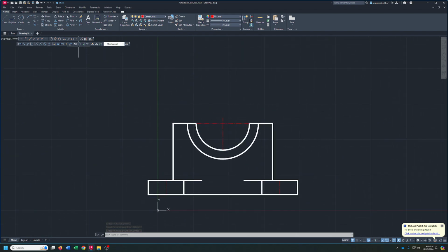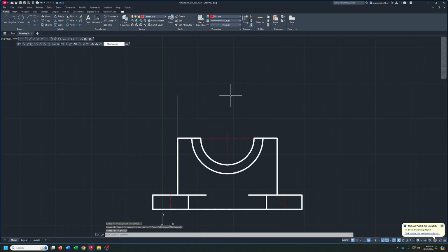Now, we look at the top is what we're going to use so that we can get our hidden lines, okay? Remember I said like 1.5 away? We might go a little more to that because this is a pretty big drawing. So we're going to have to do it at a different scale. So that would be 1.5 around here. 1.5 inches around there. So let's go twice as far. Let's go 3 inches. Let's put that on the construction line layer. So that's where we're going to start.